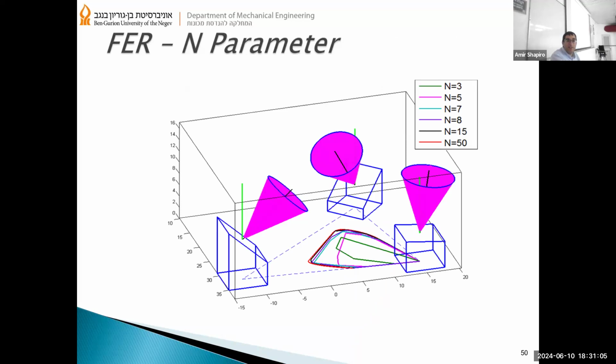And the idea is that if the robot legs touch the ground, as you can see here, and they touch such that the friction cone does not include the vertical line, you see the vertical line, and you see the normal to the contact, and the vertical line is not inside the friction cone.